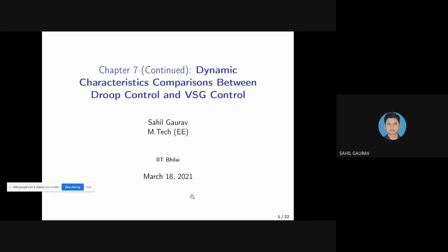So, in the last lecture, we saw the basics of inverter interface, distributed generators, control types of grid-side converter, principles of VSG control, and functions of the synchronous block, governor block, and QV droop block with PI in the VSG control mechanism. We also saw various other inverter control methods with virtual inertia, which are analogous to VSG and were developed in the past. And we also saw the comparison between them.